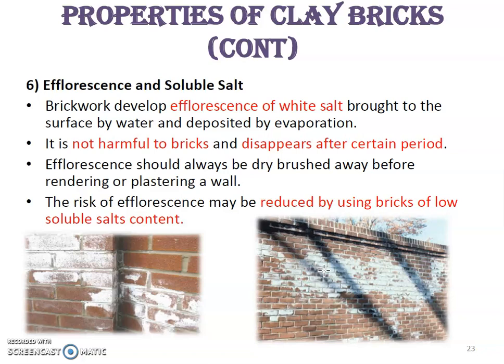This white spot is actually not harmful to bricks and it will disappear after a certain period of time. But we need to prevent the deposit of the white salt. How? We need to dry brush it away before rendering or plastering a wall. Or we can use bricks of low soluble salt content.